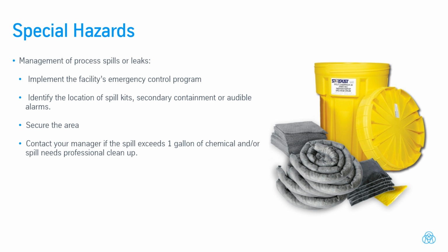Special hazards. Management of process spills or leaks. Implement the facility's emergency control program. Identify the location of spill kits, secondary containment or audible alarms. Secure the area. Contact your manager if the spill exceeds 1 gallon of chemical and/or spill needs professional cleanup.